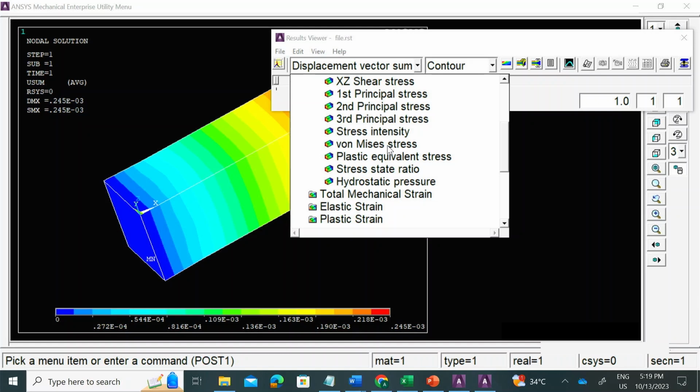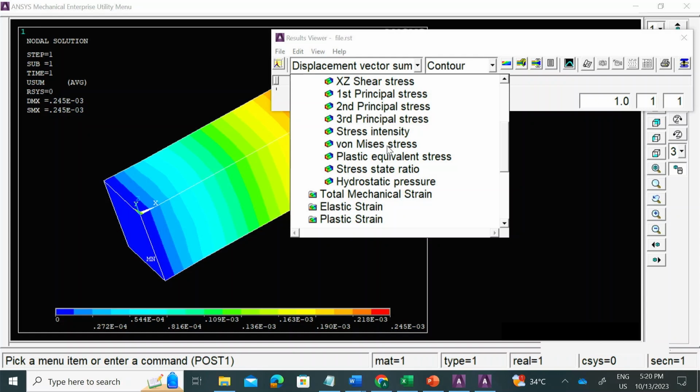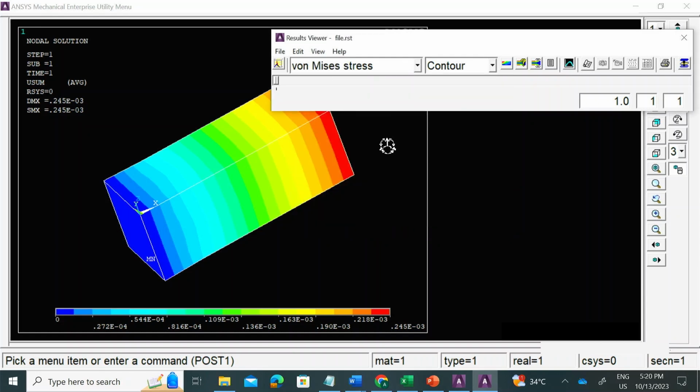It gives us a very nice flexible single value of stress which can also handle very large deformation. So this is a stress equation which gives a very accurate value for complex simulations involving a lot of contact pairs, non-linearities, complex shapes and things like that. So von Mises is a rule of thumb, just like SOLID186. We always go for von Mises.